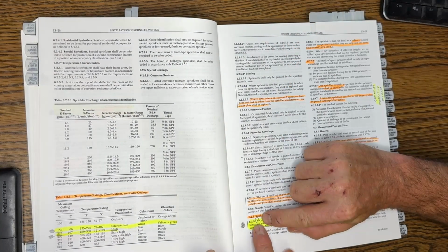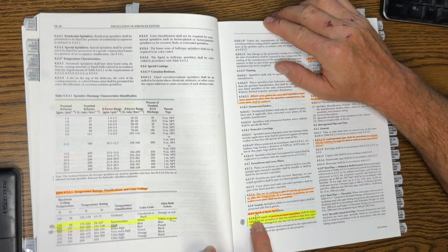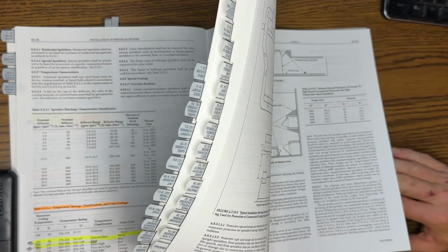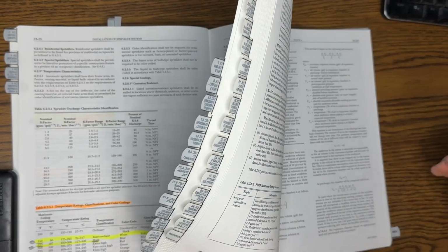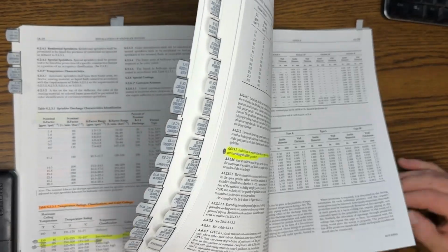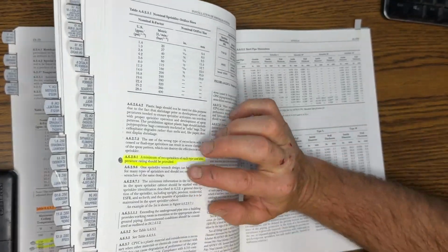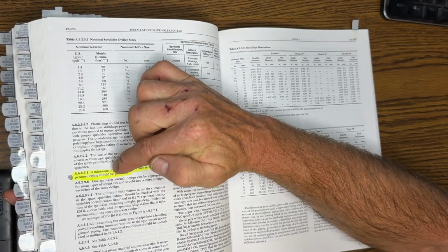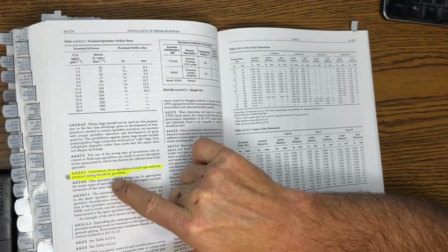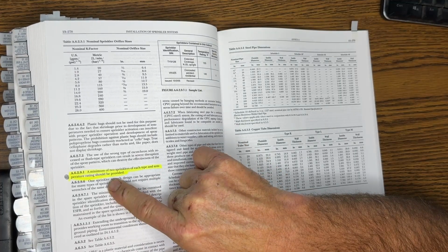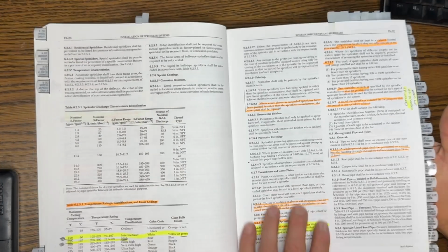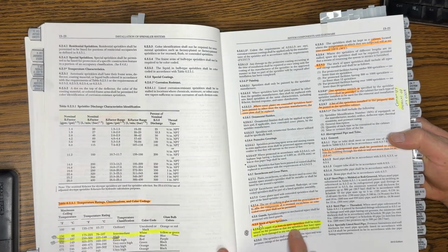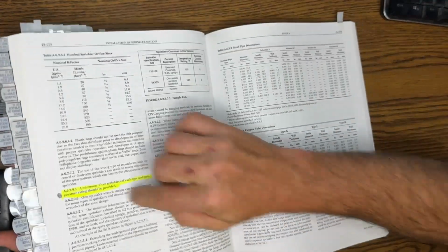Now look at the circle here. This is important. What that circle tells you is go to the annex, and Annex A specifically. Annex A is what NFPA refers to as appendices. Instead of calling it an appendix, they call it an annex for some reason. But let's go to 6291. A minimum of 2 sprinklers of each type and temperature rating should be provided. So go to the annex when you're trying to answer complex problems. If it didn't have an annex reference and it just said at least 6 spare sprinklers, that'd be the answer. But go to the annex and find out more.